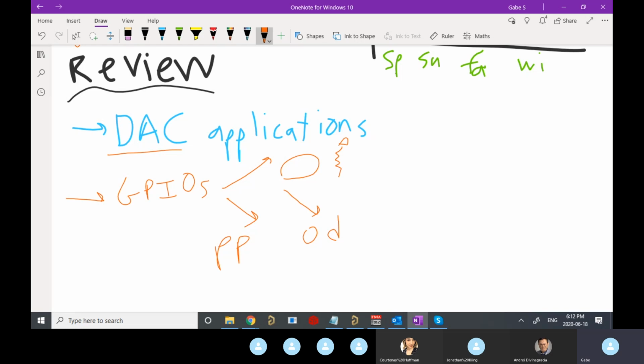Right? And that allows us a number of different things. That means the user can choose the logic level they want up here with whatever pull-up resistor they put. It also means that we can have multiple systems sharing the same line and have an ORing logic towards them so that they don't accidentally send any shorts. But in general, you'll see an application of this today when we talk about serial communication protocols.